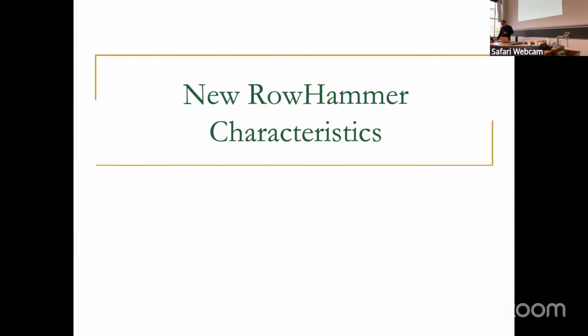Another thing that's good to think about is, we talked a lot about processing in memory, processing using memory. It's good to think about how that interacts with ECC. So it's good to think about whether you can design ECC mechanisms that enable processing in memory or processing using memory to work nicely.